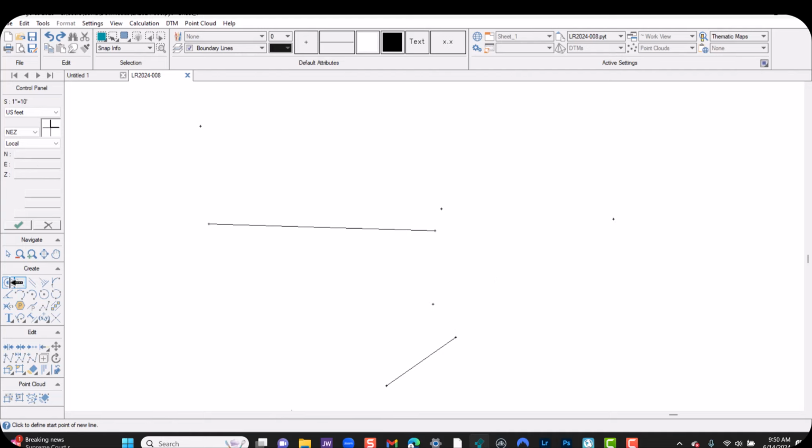One other point, let's say that I wanted to set some points on the line, but I want to set one right in the middle of the line. So I highlighted my point tool. If I hold down the 2 key on the keyboard and slide across the line, it'll show me where that center point is, right there.